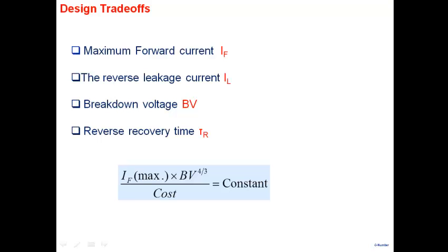And this will tell you also, for example, an expression like this tells you why, when you go and look at a manufacturer, you'll find hundreds or thousands of diodes. Why is it there? Because different diodes strike different compromises between these parameters. In some diode, I have a current of 1 ampere, breakdown voltage of 100. Some other diode will compromise on forward current and increase the breakdown voltage. And therefore, you have a variety of semiconductor devices. Why? Because of trade-offs.